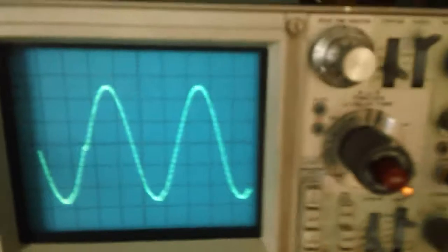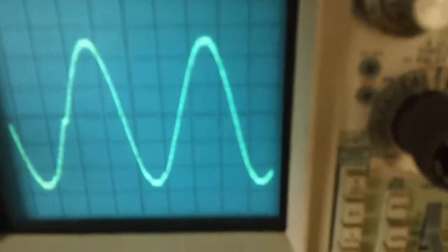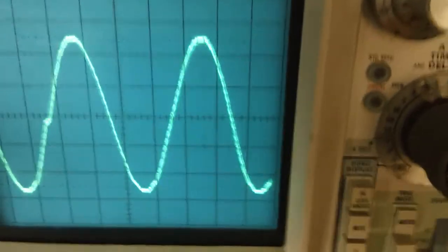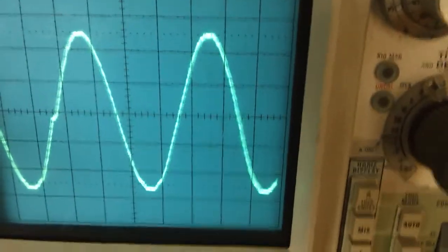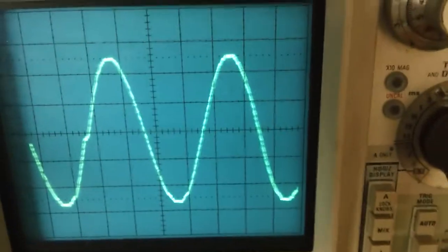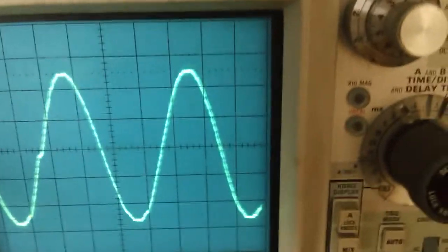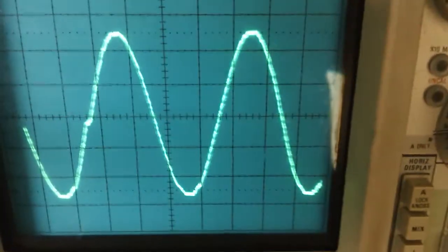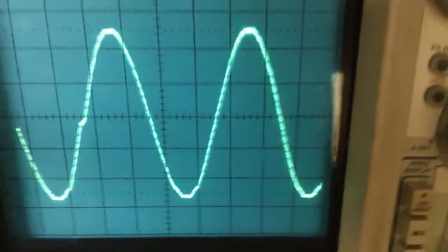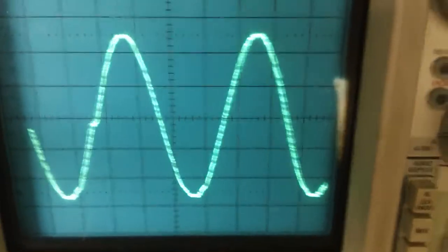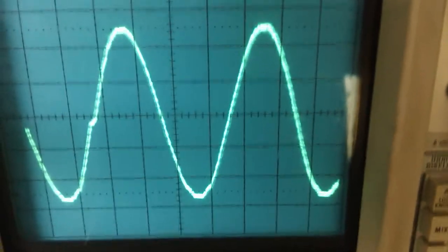And we have a sine wave, ish. Now, if you look carefully on the rising edge, there is a little bit of jitter, and that's because of the way that I generate the sine wave. The Arduino, powerful little computer that it is, you can't actually use the sine function in real time, because the sine function is pretty slow. So what I've got is a lookup table.